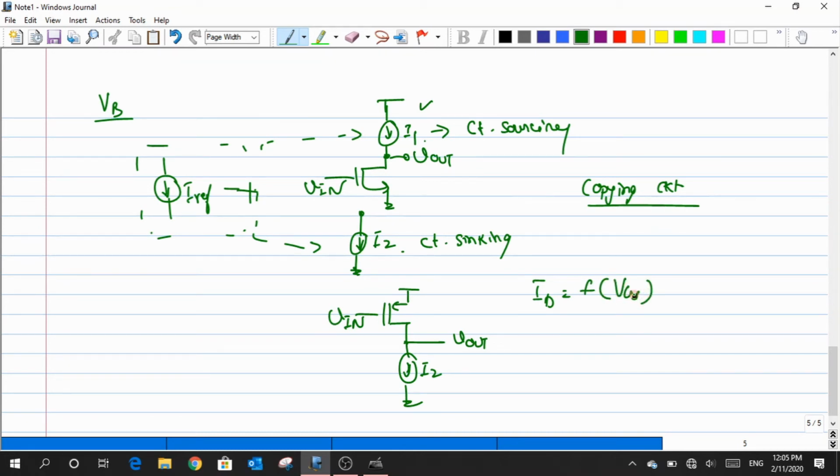It's basically a function of VGS, right? The current that flows. But what we wanted is a VGS out of it. I don't want the current, but what I rather wanted is the value of VB or the VGS to these loads, right? To these loads, what is really required is the value of VB or VGS. So what I can do is perform something known as an inverse function. I need an inverse function that acts on the value of ID such that it generates me back the value of VGS.